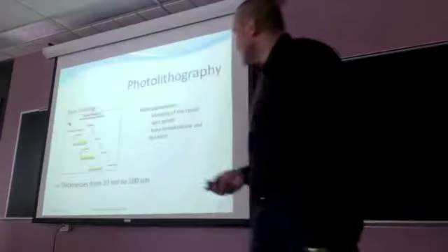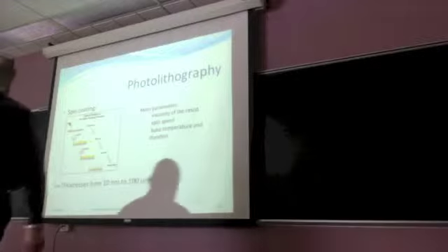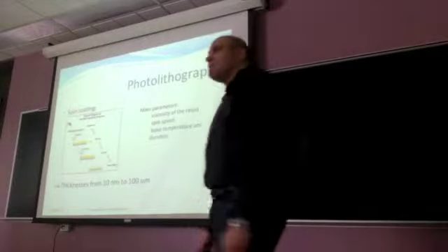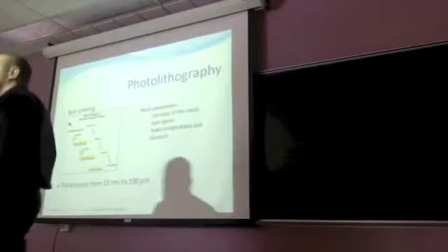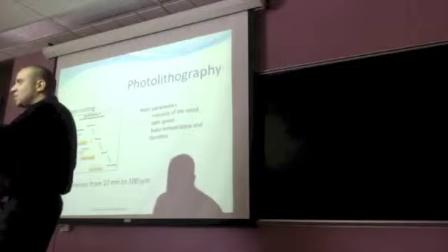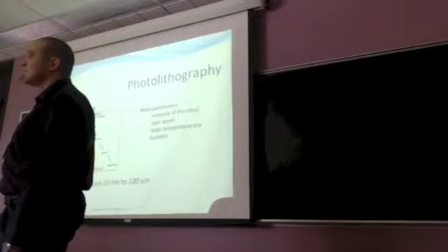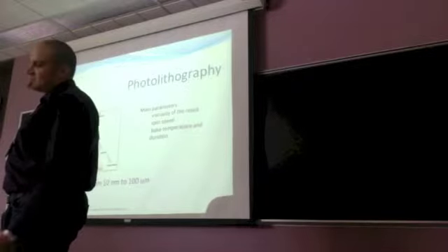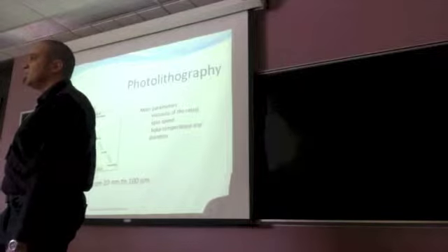But your 3 by 3 millimeter sample, couldn't you stick it on another wafer to use it as another substrate? Yeah, of course. You can do that for reactive ion etching, for example, for plasma etching. But for photolithography, it will be very difficult, I think, because the pressure will be applied only on this small sample, and I'm not sure it will be uniform. One solution could be a spray coat, right? Yes, of course, spray coating can be a solution to dispense resists. But I will not talk about this technique.